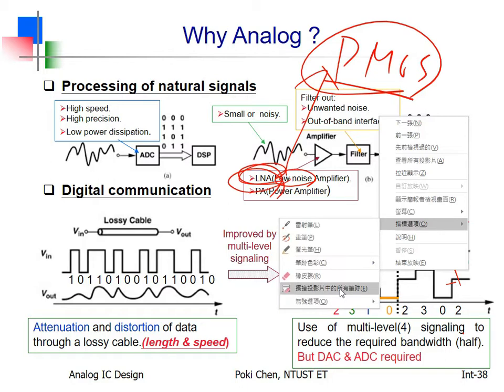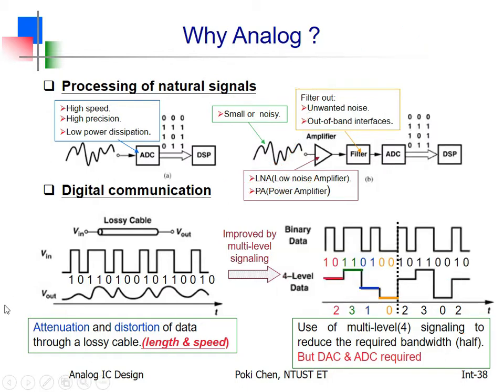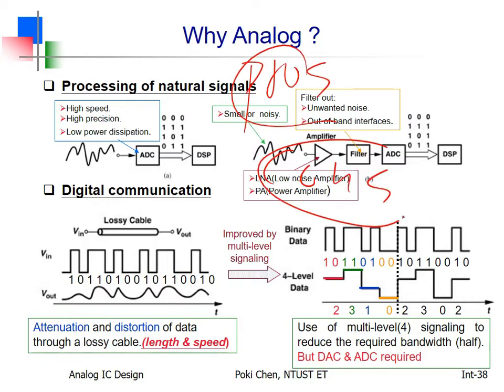For speed, nothing is free. For speed, NMOS is much better than PMOS. But for noise performance, PMOS is much better than NMOS. That is, from the very beginning, you will see the world is not ideal. It's imperfect. Nothing is the best. We always have the so-called pros and cons, 优点跟缺点. You need to accept it.